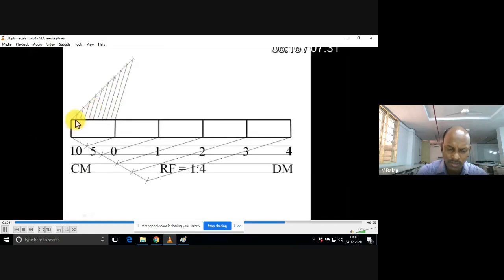Then you can drop vertical lines, okay, with the help of the mini drafter again. See here, you have drawn so many parallel lines with the help of the mini drafter. Simply loosen the mini drafter knob, then match your mini drafter scale to the horizontal lines you have already drawn, then tighten the knob. Automatically the other scale you can use for drawing vertical lines.